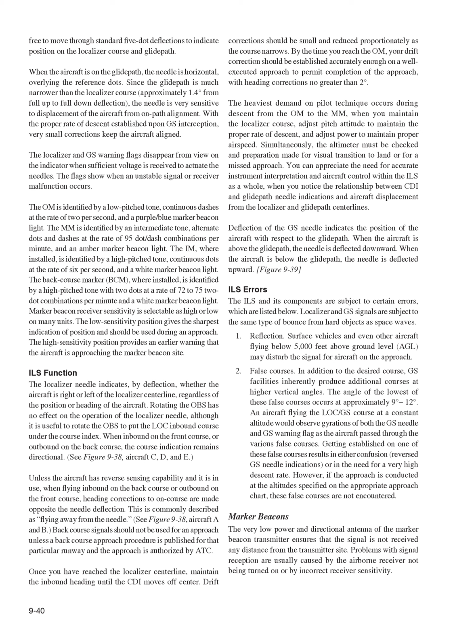Drift corrections should be small and reduced proportionally as the course narrows. By the time you reach the OM, your drift correction should be established accurately enough on a well-executed approach to permit completion of the approach, with heading corrections no greater than 2 degrees.